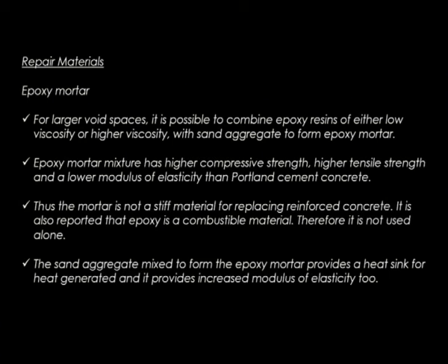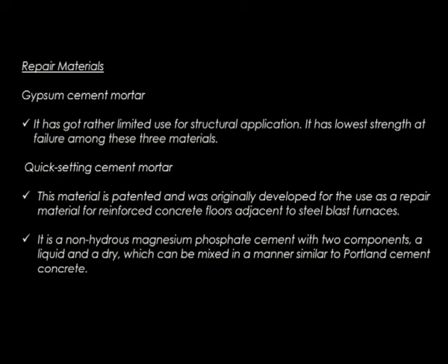So, epoxy mortar mixture has higher compressive strength, higher tensile strength and lower modulus of elasticity than Portland cement concrete. Thus, the mortar is not a stiff material for replacing reinforced concrete. It is also reported that epoxy is a combustible material, therefore, it is not used alone. So, this is the most common repair material that we use, the epoxy one. The sand aggregate mixed to form the epoxy mortar provides a heat sink for heat generated and it provides increased modulus of elasticity too. The next is the gypsum cement mortar.